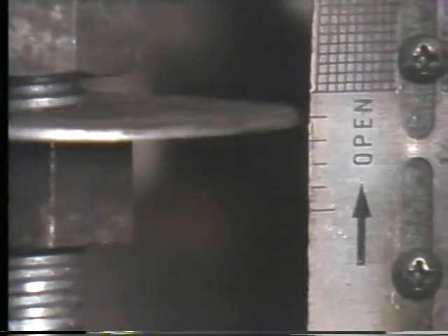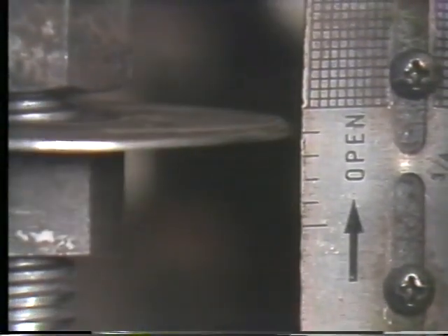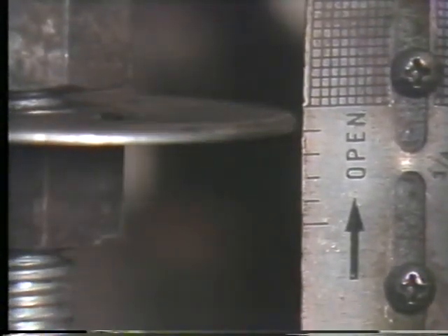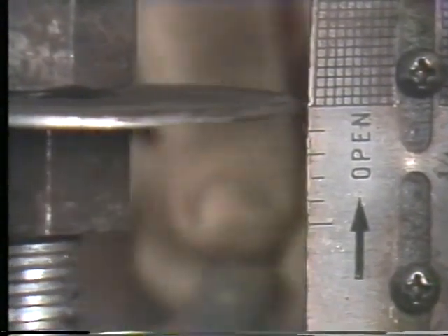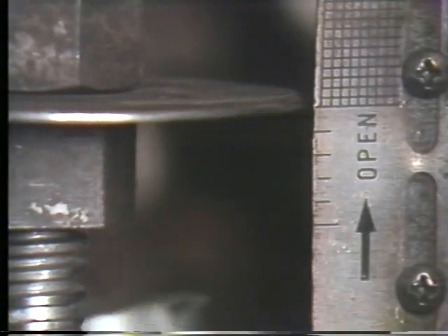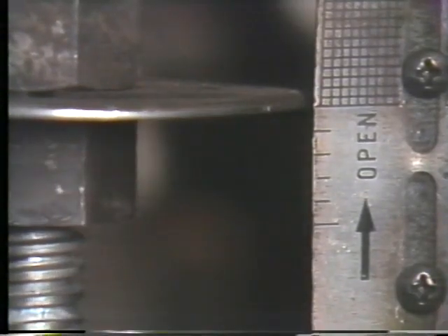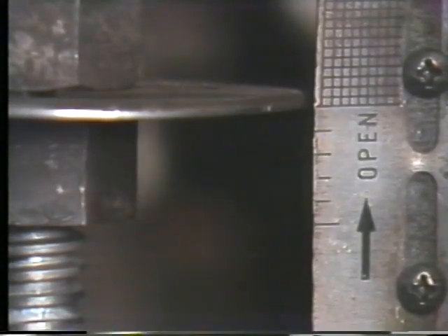Continue raising the valve in this manner until the travel indicator plate on the valve stem is lined up with the high mark on the travel indicator scale. You should understand that we did not change the position of the indicator plate on the valve stem. Instead, we connected the valve stem to the actuator stem by raising the valve to its fully opened position.